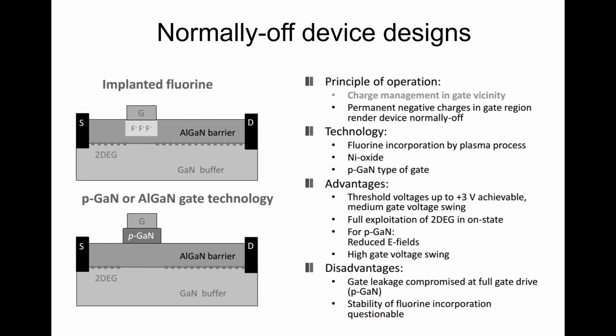So that's some other approaches, like the implantation. There were many papers on fluorine implant that you may have seen in the literature. I just put a cross here that it's not really working. Again, this works perfectly. You can shift, you can even fix the threshold where you want, depending on the dose that you use with fluorine. So that works very nicely. I think we've done that at IME 15 years ago or something.